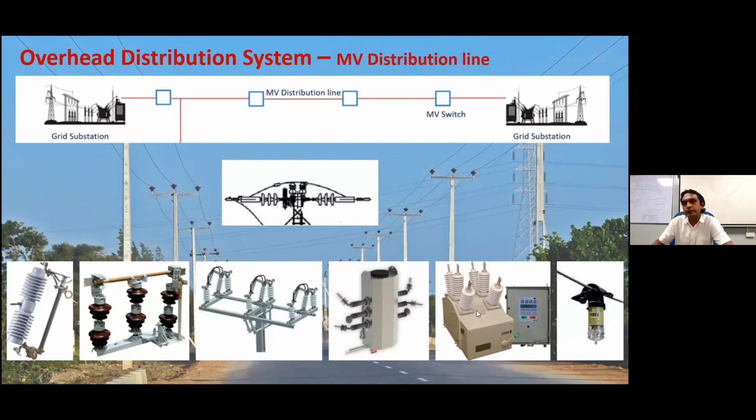But when we move to this one, this is another type of switch. As I mentioned earlier, it's called an auto recloser. It actually comes with another intelligent device we call the control box. The control box mainly consists of a protection relay. It always observes the condition of the system, and it gives commands to the control unit of the auto recloser.